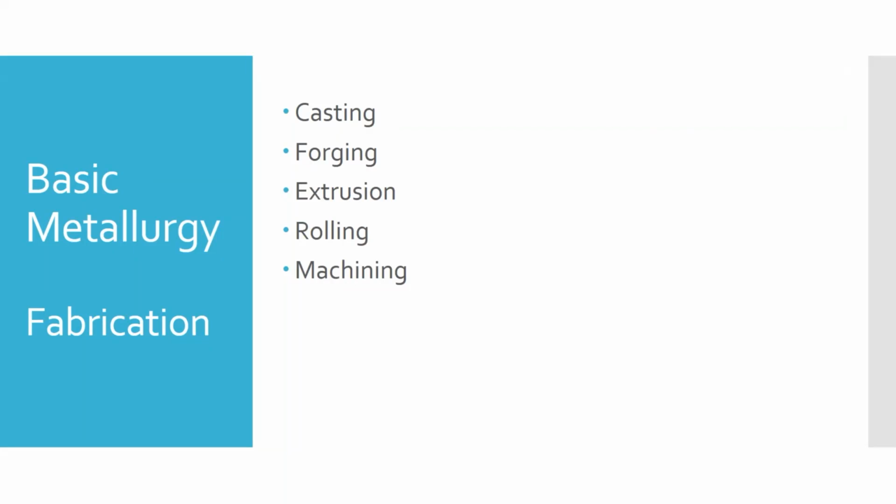And all of those can leave different types of finishes on the surface that can cause different types of indications. So for instance, castings and forgings in general create a fairly rough surface, just the raw casting, raw forging. And so that can trap dye, that can trap metal particles. That can be hard to get a good bond on when you're doing things like eddy current testing.